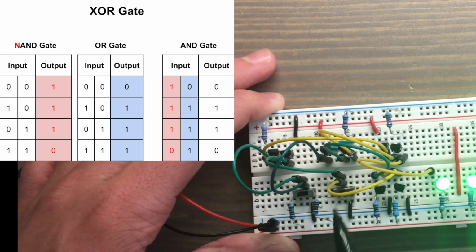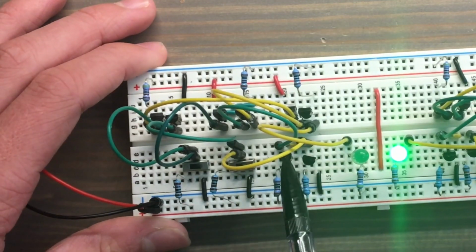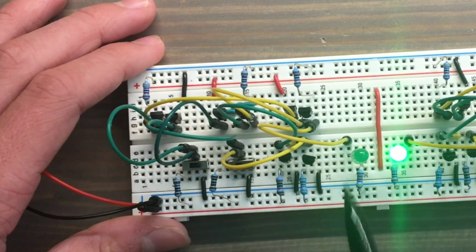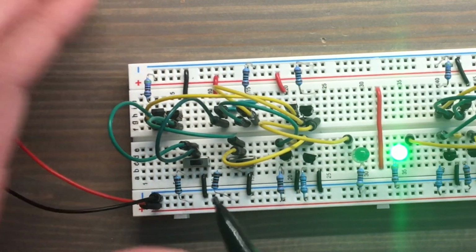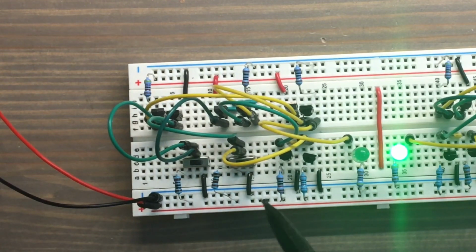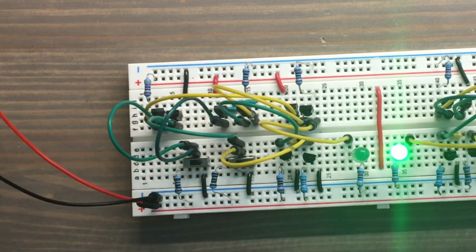And then lastly, this part of the XOR gate over here is just a double inverter buffer, and I'm only putting one of the inputs through it because that's what we need for this gate. It would probably be a good idea to do it for all of them, but this just prevents these two gates from shorting each other out because they have the same inputs going to both of them.